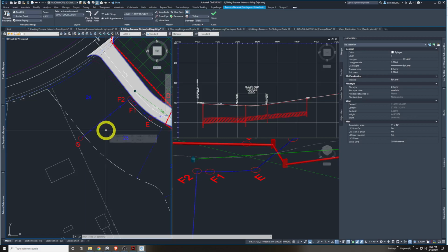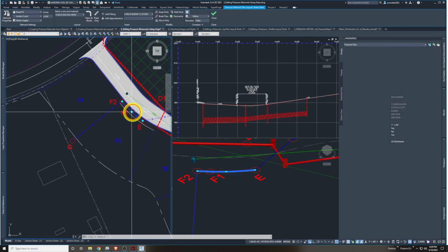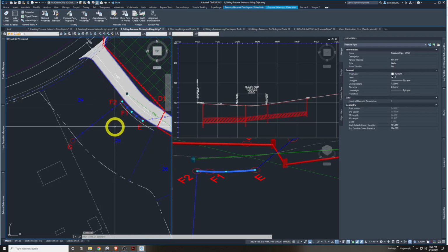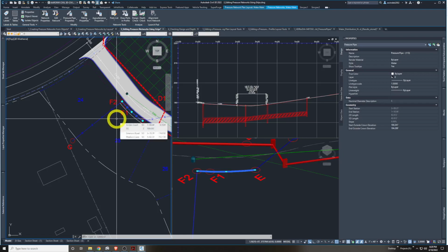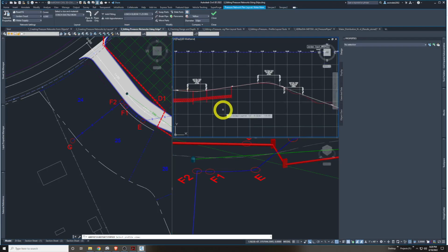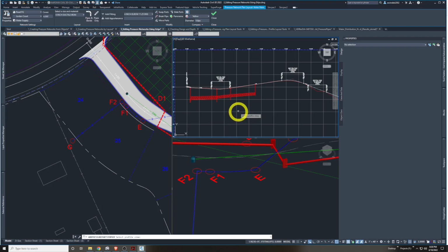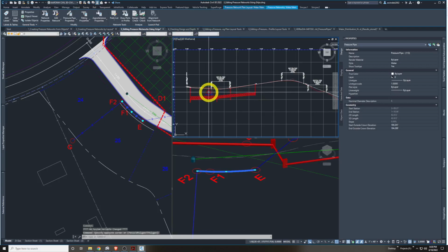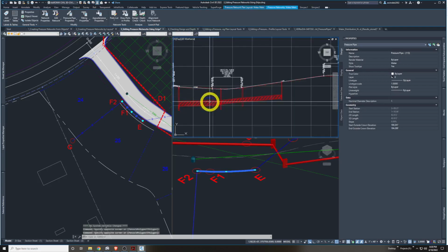So we're just going to click the pipe between E and F2 right here, which we have selected on both viewports, and we're going to draw this into profile. Let's click Draw Parts and Profile on the Pipe Networks Water Main ribbon tab right here. Now let's go to our Profile View area viewport on Jordan Court, and let's select the view. It should have added just a small segment right there. You can see how it conflicts or meshes with our sanitary sewer, stormwater, whatever that is there.